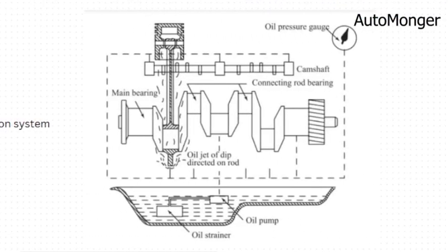For this diagram now, let me explain it properly so that you understand. Of course, I've explained this part already, the oil strainer and then the oil pump, how it works. But for this one now, when the oil strainer strains the oil and sends it through the oil pump, the oil pump will pump the oil directly. You can see this dotted line. This is the direction of flow of oil. It is pumped directly to the camshafts. You see this point, this point, this point.